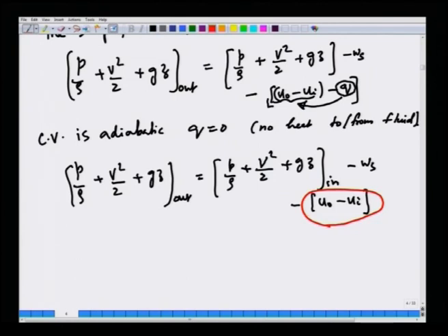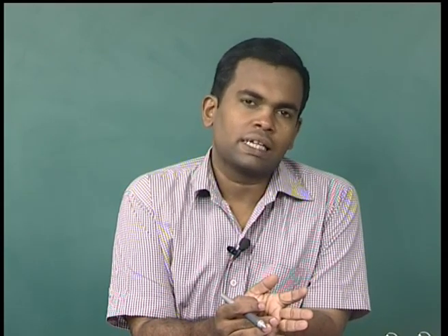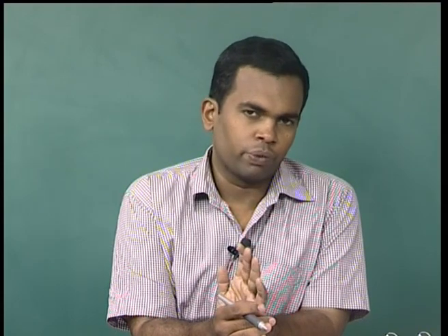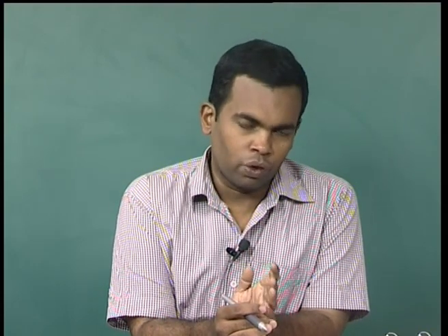Okay. So, it turns out that whenever there is a fluid flow happening within pipes or in equipment like pumps or compressors, there is always an irreversible transfer or conversion of macroscopic mechanical energy to internal energy. Okay. So, this is a fact that whenever there is a fluid flow, the viscous nature of the fluid always dissipates energy from macroscopic motions to microscopic degrees of freedom, which is essentially the internal energy of the fluid.